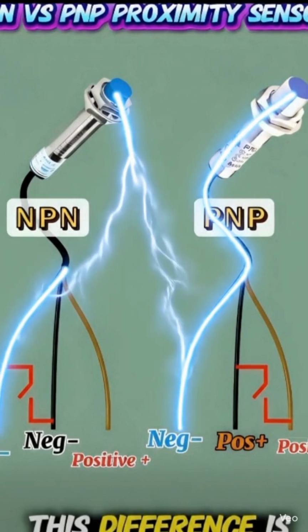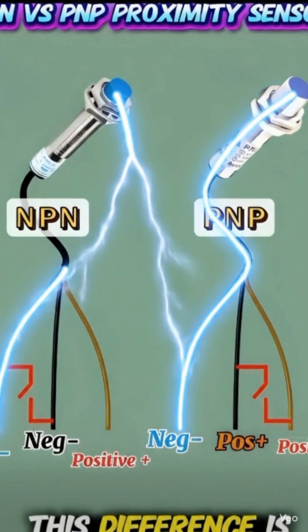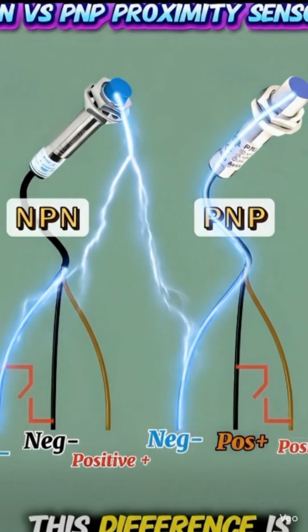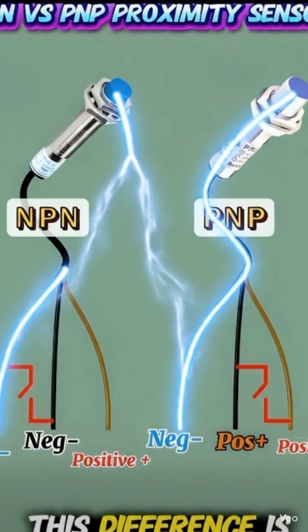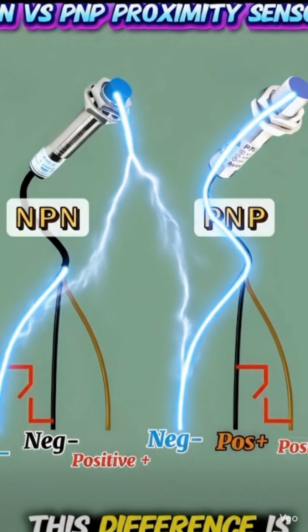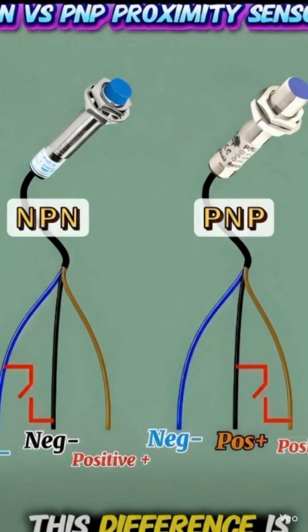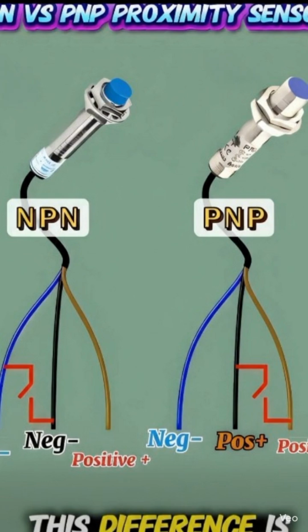2. How they turn on. Biasing. NPN turns on when the base is more positive than the emitter, about +0.7 V for silicon. A small base current flowing into the base allows a larger current to flow from collector to emitter. PNP turns on when the base is more negative than the emitter, about -0.7 V. A small base current flowing out of the base allows a larger current to flow from emitter to collector.